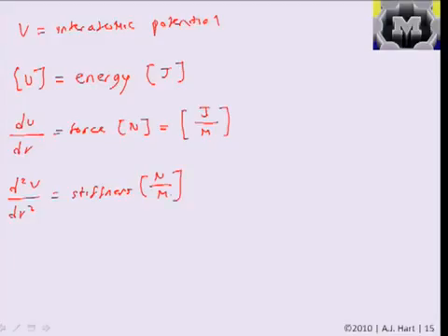So you may have already seen this in the question on the problem set, where we try to consider the mechanical properties of the hexagon and give you the potential function. By taking the first and second derivatives of these types of functions, we can get the idea of a bond stiffness. There are many different ways that these functions are derived, but for now we can just take it as given. And I'm going to call this stiffness S.